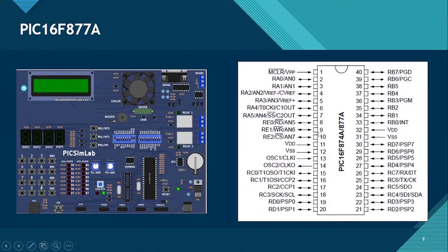So let's talk some more about the microcontroller that we will be incorporating in our project. It's the PIC16F877A microcontroller that we'll be using in our project to simulate the output. PIC16F877A has multiple on-chip peripherals. Like I said before, it has 5 ports, 3 timers, LEDs on the development board, capture compare modules, analog to digital conversion, a comparator, and so on. Let's have a brief look at some of the on-chip peripherals and some peripherals that we will be interfacing in our project.